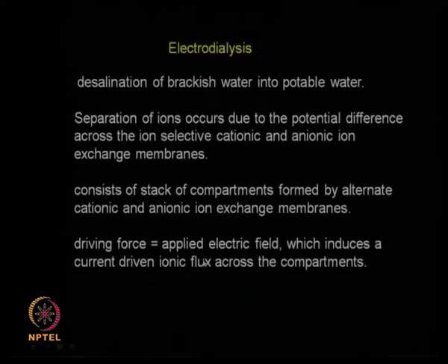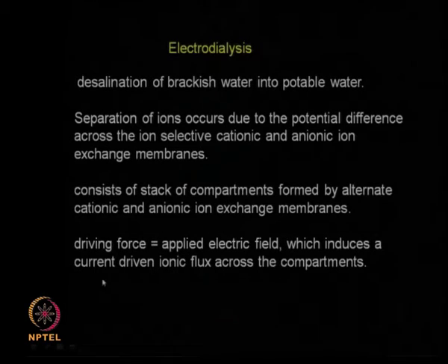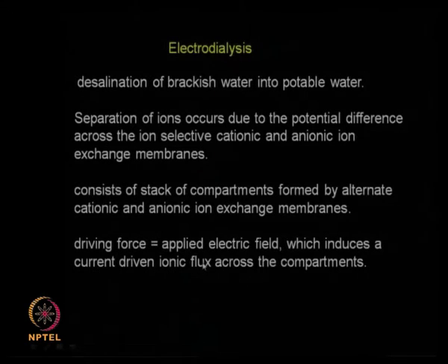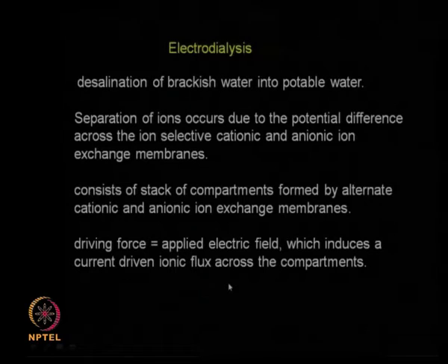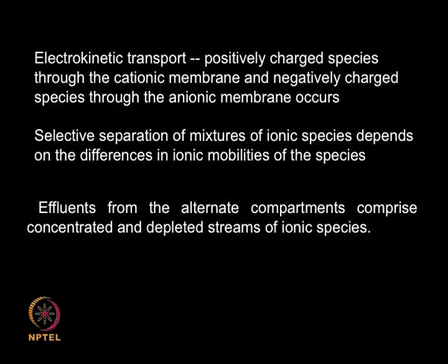So the driving force here is what? There is an applied electric field. Now this induces a current and there is a flux across the compartments. This is what happens in an electrodialysis. So positively charged species go through the cationic membrane, negatively charged species go through the anionic membrane, and because these membranes are very selective, the other type of charged material will not go through the non-selective membrane.